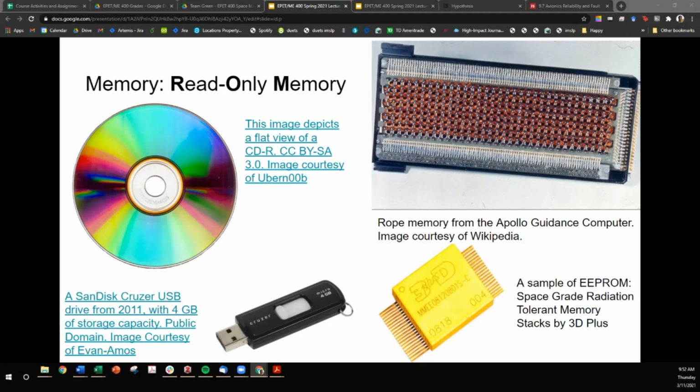Read-only memory is, as the name suggests, read-only. This type of non-volatile memory is defined by the manufacturer and cannot be changed. This is typically advantageous for storing software that does not change throughout the system lifetime, usually dedicated to firmware. Although read-only memory can be reprogrammed with special instructions and some specific voltage setting, read-only memory can only be rewritten a limited number of times.